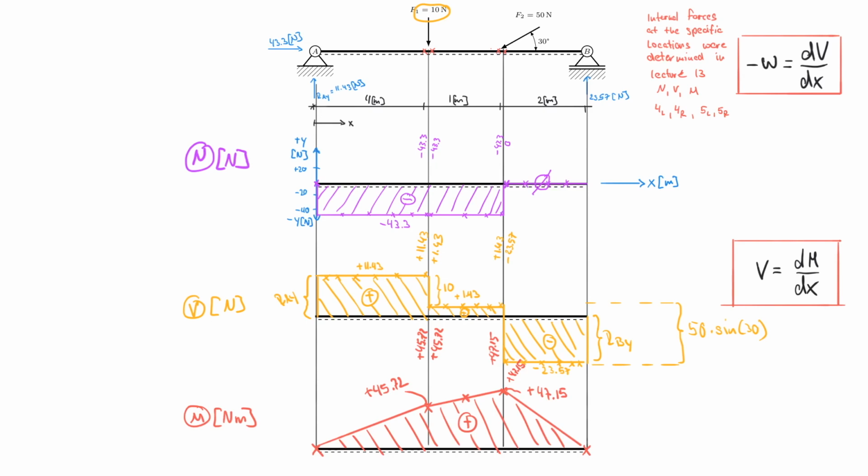We said that a smiling beam that would bend downwards has a positive moment on it. That's defined by the moment that turns clockwise on the left cut and counterclockwise on the right cut. Take a look at your note card. So we said that those moments always create a positive bending. And you can see this here in this diagram. So you can see that this beam must be smiling all the way from here to here, because from 0 all the way over to the 7 meters, the beam is smiling.